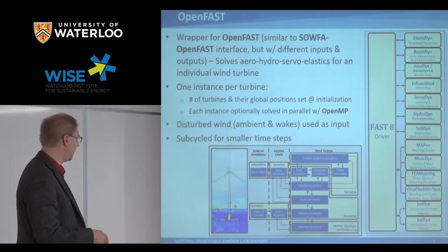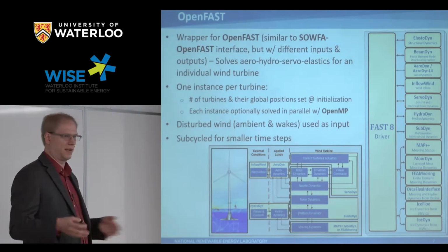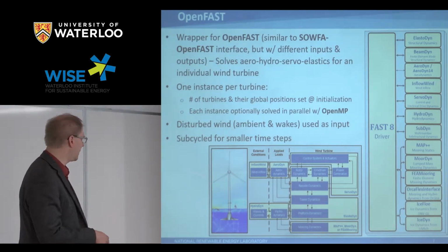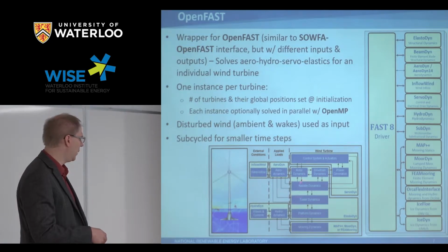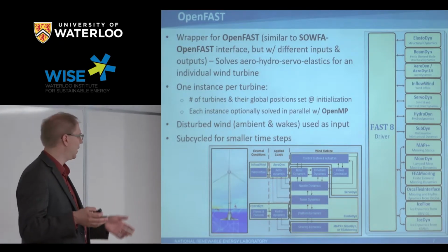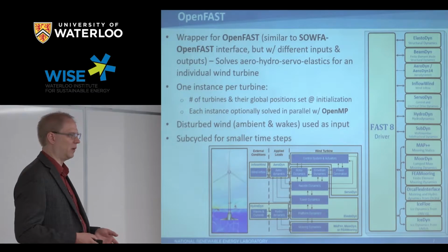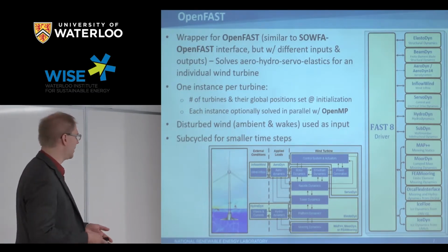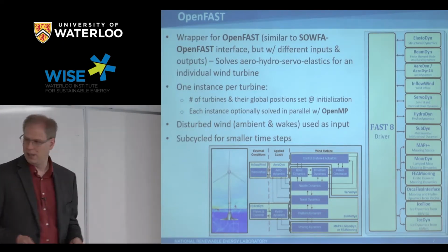These are usually on the order of hertz, 10s of hertz, and so you want to run these at a fairly small time step, about 0.01, whereas wakes are driven more on the scale of seconds, and so we have the ability in our solution to basically solve the wake problem on the order of seconds, and we subcycle at a much higher frequency to get the actual structural loads out of the turbines.